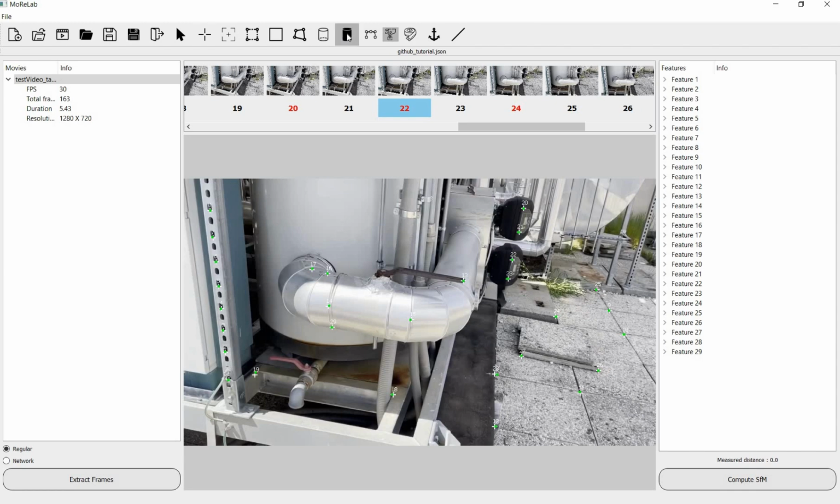The next one is the base cylinder tool, which is actually more useful in most cases. In many situations it can happen that the center is not visible, like in this case. So we can make use of the points that are on the surface. I have these 3 points on the surface, and I will click on them, and then the algorithm will try to estimate a circle that passes through these 3 points. Once I click it, it estimates a circle that passes through these points, and after that I just provide the depth of the cylinder to have the final cylinder shape.